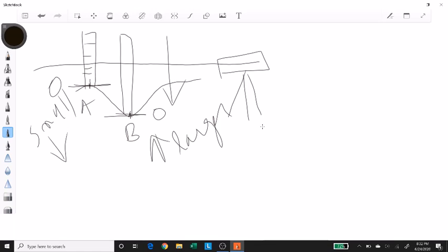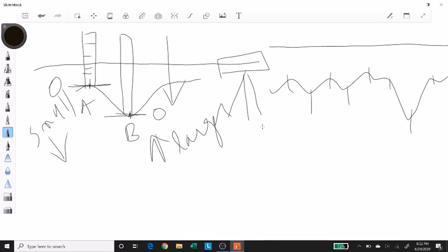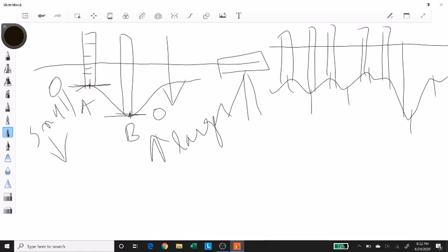By using this instrument, you can quickly find out height difference between a lot of points. So if I have a very difficult terrain, I can just place my instrument at one location, and this becomes my line of sight, and I can find out heights of different points just by taking my staff, placing it at all the points whose elevation I want to know without moving my instrument. So this really speeds up the process of finding out height difference between different points.